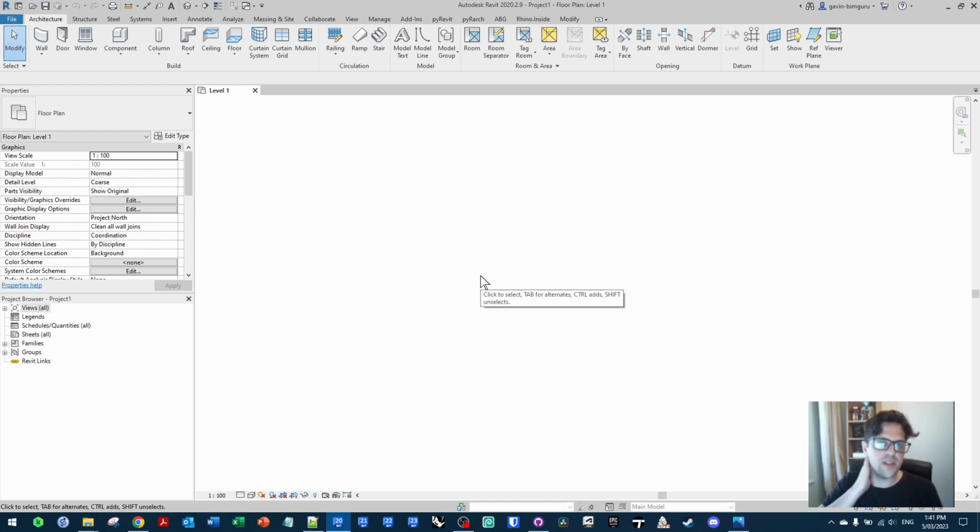I believe you'll run into the same problem if it's in a group or an array, where it will try to ungroup the arrays, and generally the family manager will skip over these parameters and give you an error. So you won't be able to run this on any families that are using associated parameters on an instance basis to nested arrayed components. One workaround for that is to associate on a type basis to non-shared components, but it doesn't always work in every scenario.